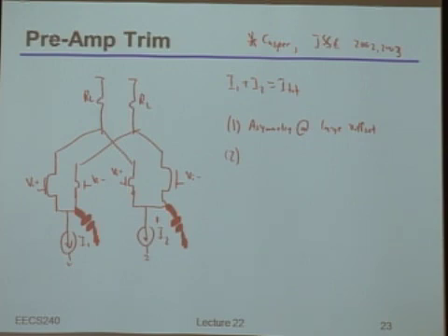Okay, great question. So you said, hey, wait a minute. The comparator offset is a voltage at the output of this thing. So you're absolutely correct that the comparator offset is basically attenuated from an input referred standpoint by the gain of this structure. Right, so if the gain of this structure is high, then really, in some senses, you're only canceling your own offset. Right, because the comparator offset relative to the input has a smaller effect. Having said that, for better or for worse, you're probably not going to be able to get very high gain out of this thing. Because again, remember we said that we wanted these load resistors to be small compared to the RO, which tends to push us to relatively low gain types of topologies.